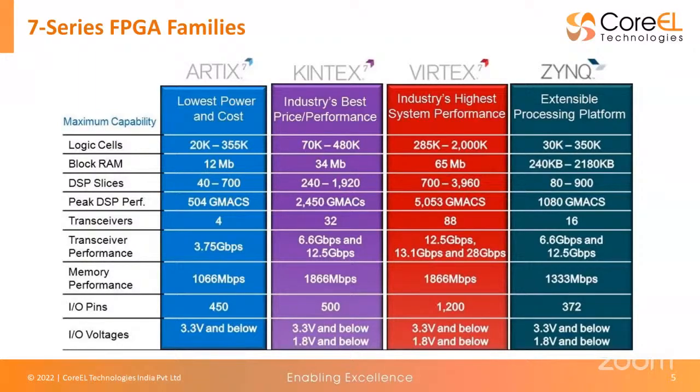At the other end of the spectrum, you have Kintex and Virtex chips, where you will be able to see a much higher number of logic resources. Not only that, you will also see much higher end RAMs, the memory blocks as well. Where do we use Kintex and Virtex chips? It's about the computational power that comes within the FPGA itself, right?